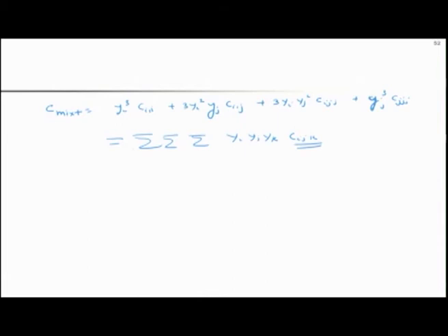Now in order to obtain this cross coefficient, we need to find a significant amount of experimental data, and I won't go into details of this, but let me first write down the Z mix here, which is PV by RT for the case of the mixtures. So earlier we said that we would just consider the second virial coefficient truncated version, but if you want to add this and somehow you can obtain this, then it would be very useful. Okay, so you can use this expression and obtain your fugacity coefficient.